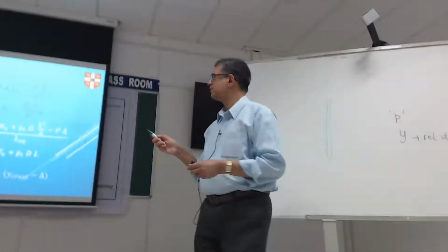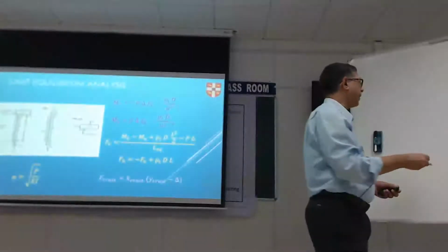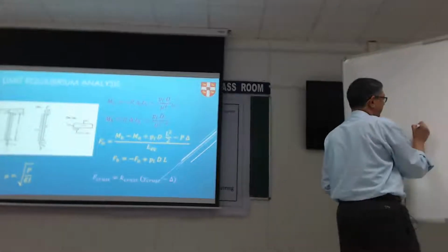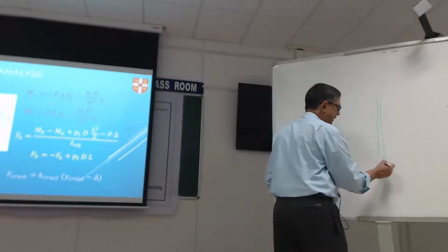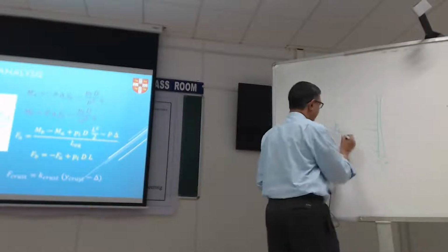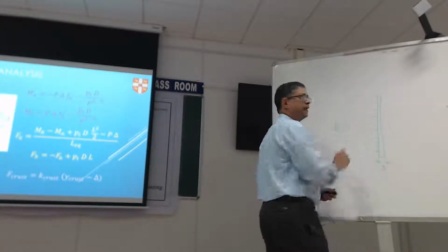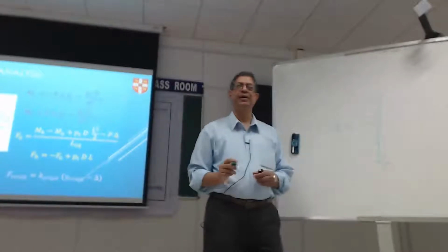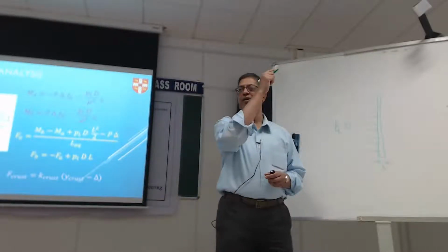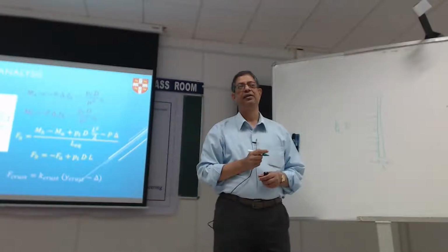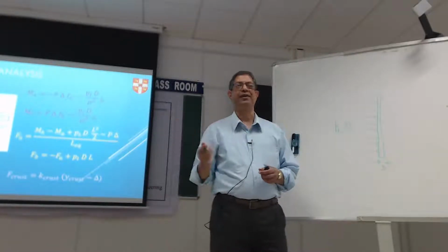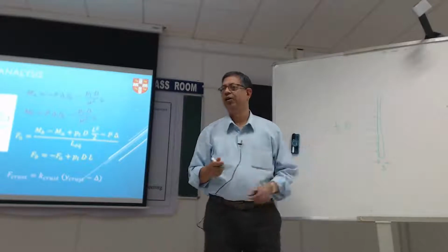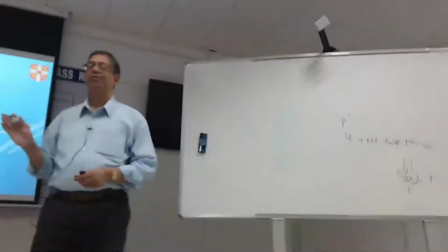Yeah. Let's say that the liquefied soil is going to apply a pressure of PL and the diameter of the pile is D. So PL times D gives me the uniformly distributed load equivalent. Pressure times diameter must be kilonewton per meter, right? So that should be like a UDL on the pile inside.